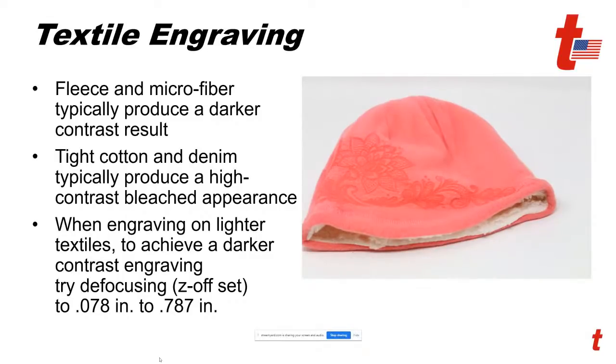With cotton, like on a denim, if you have a black denim, sometimes it doesn't work where the blue does, just because of how the wavelength of laser light is absorbed into the material and how much heat it absorbs. We'll get into some techniques on how to reduce that, like wetting your fabric down, in a little bit.